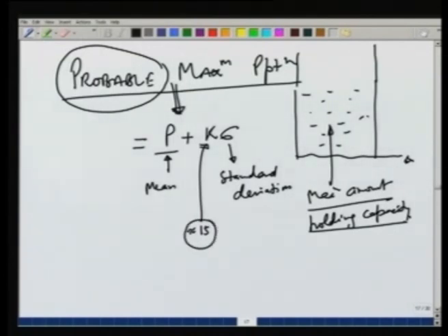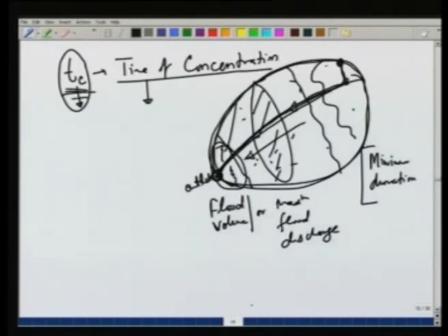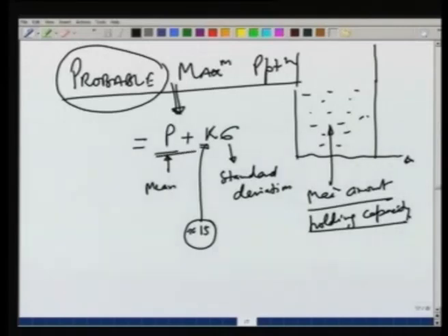So, as we saw, intensity was also important, but the probable maximum precipitation is also important. The intensity, as we saw, could be obtained from this curve. Intensity is also important in deciding, let us say we have some soil erosion in an area, the erosion can be correlated with the intensity. So, for that purpose also intensity becomes important. For maximum flood, of course, we want to be very safe, so we can use this kind of equation.